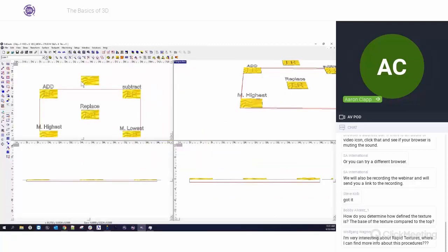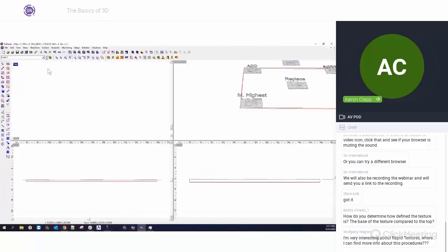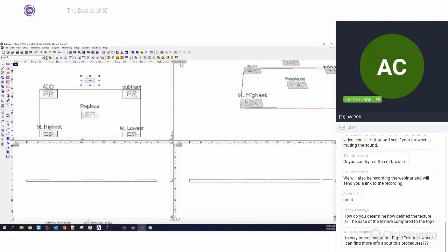So what I did was similar to what we have back here. If we go undo, when I selected my letters, I selected the letters in the relief, I hit add, I chose the merge highest, and then I set my height to 0.25 inches. But when it created the relief, it says merge highest.